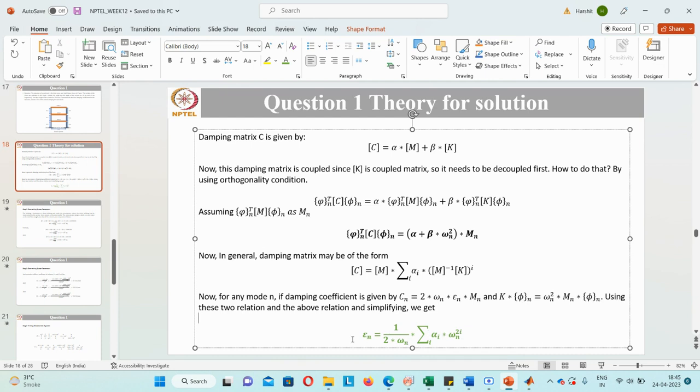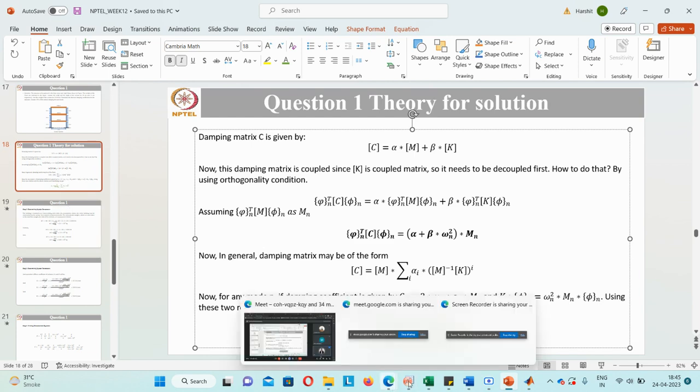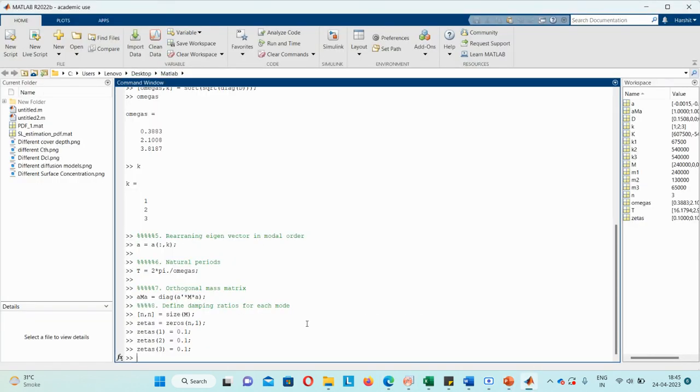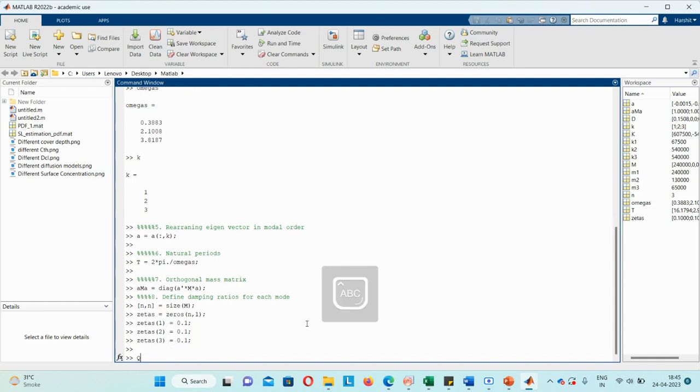So when you write this equation in the matrix form, you will obtain the relationship that I have just said. So I will just write that relationship. We will define that by Q. So Q is nothing but omega_1, first mode of vibration, omega_1 cube, omega_1 to the power 5. So this is the first row.